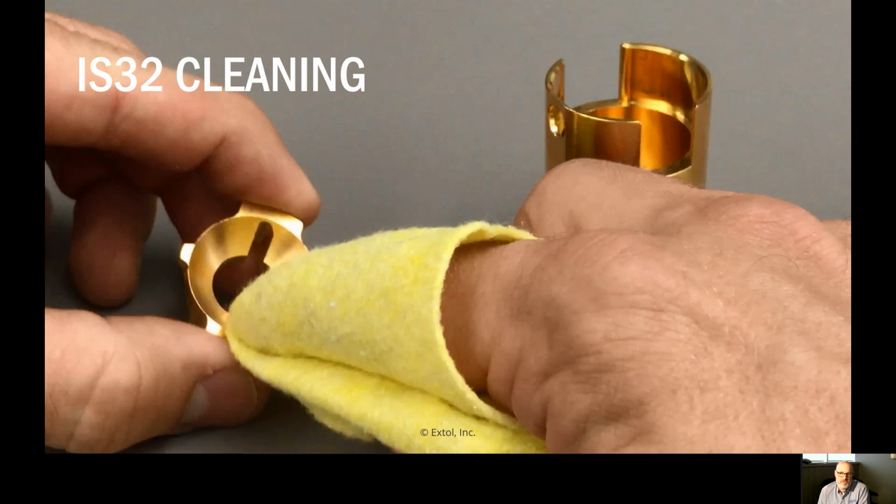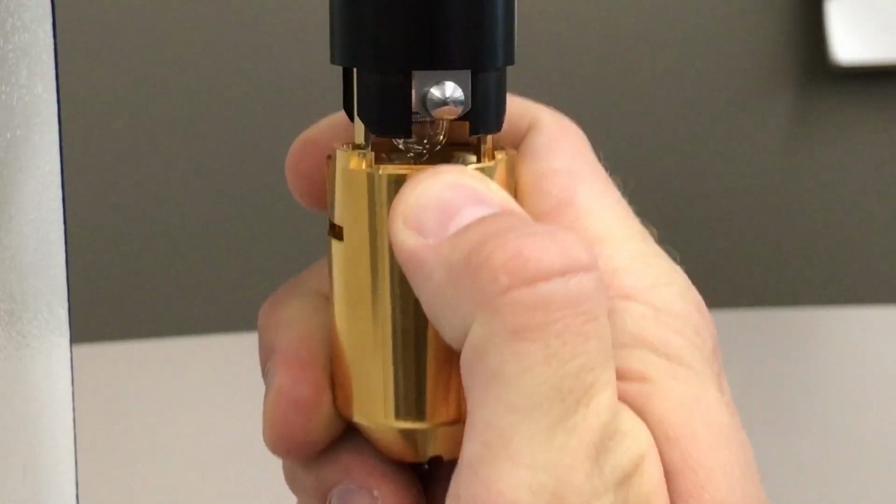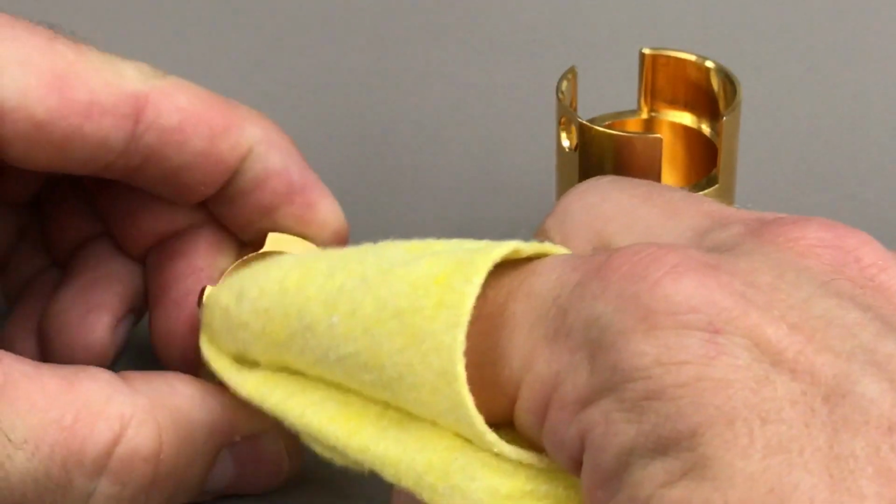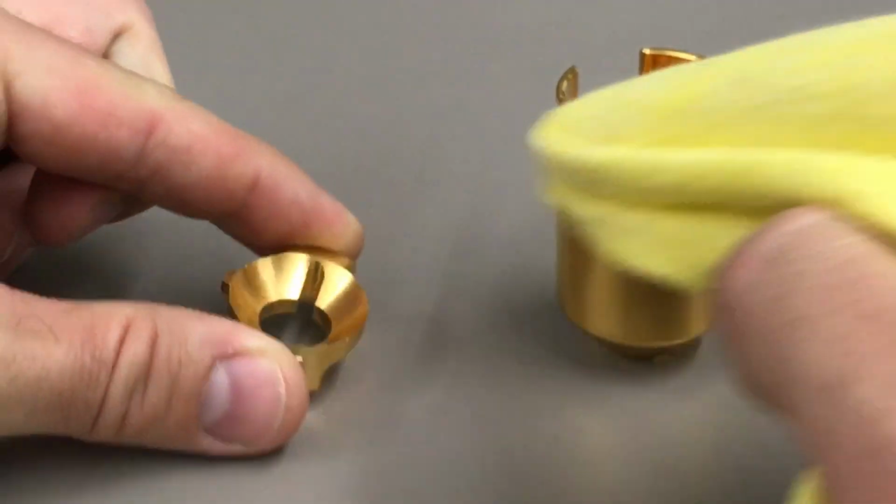This happens to be out of an IS-32. The reflector and the concentrator slide out. Again, no tools. It's just got a detent ball that holds everything together. You pull these parts apart and you just wipe them down with a non-abrasive cloth.